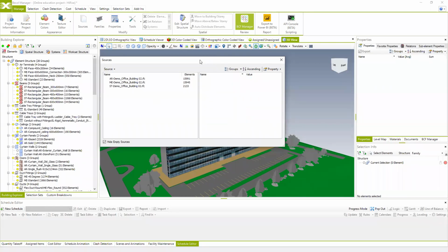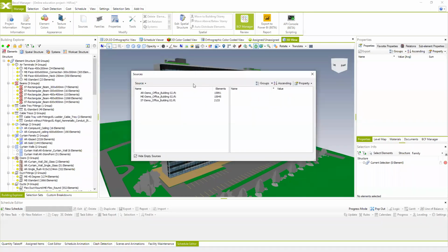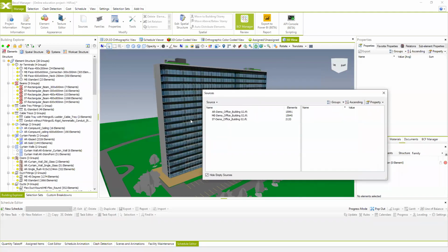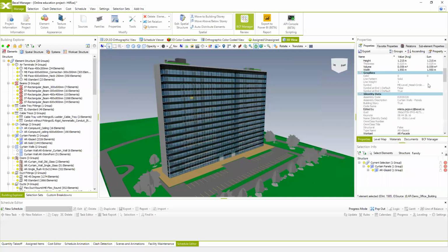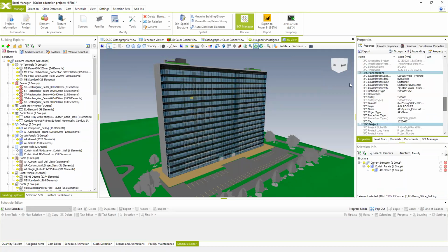So that's why we can use the same methodology and zones, because the entire project is created using the same type of BIM model segregation. So we have structural BIM model, mechanical, and architectural. And these are from the IFC files. So you see the properties are related to the IFC properties as well.